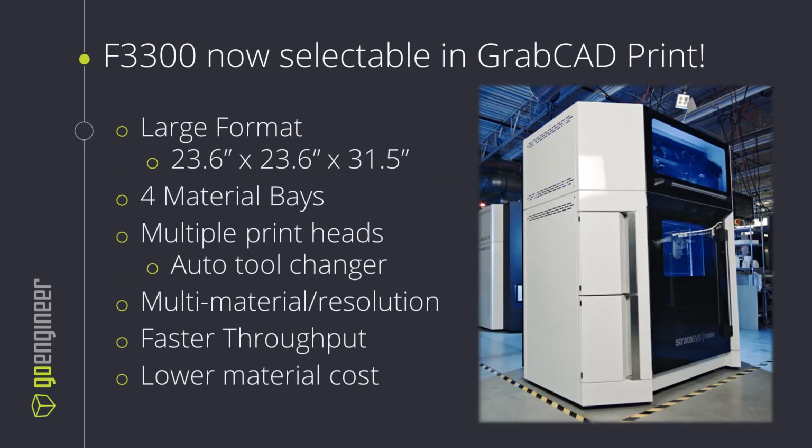If you hadn't heard yet, there's a new system available from Stratasys, the F3300, which is now selectable in GrabCAD Print for users to tinker and get familiar with. This is a large format printer. The build size is roughly 24 inches by 24 inches by 31 inches, and it holds 4 materials. It has multiple print heads, each using those different materials with an auto tool changer.